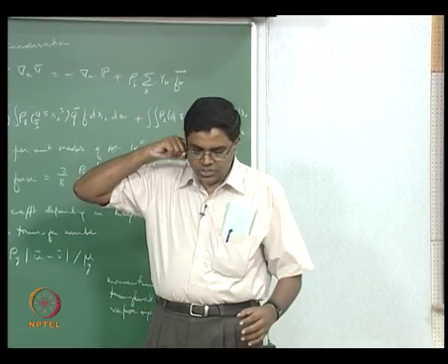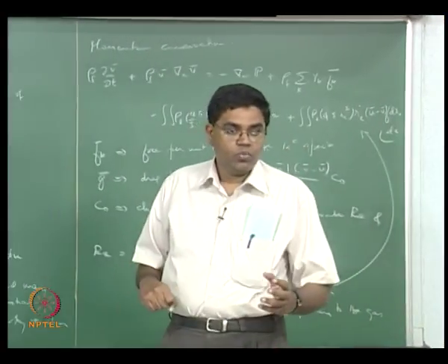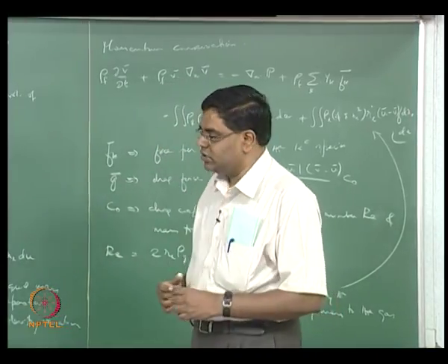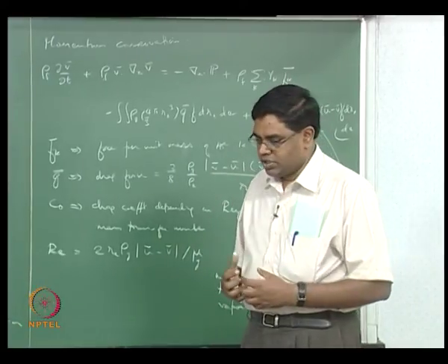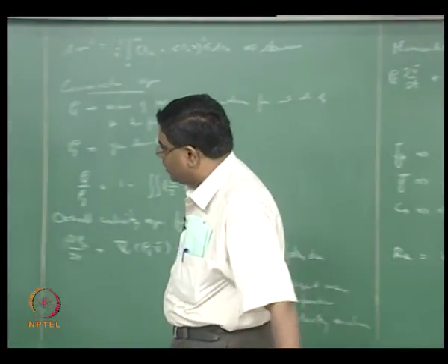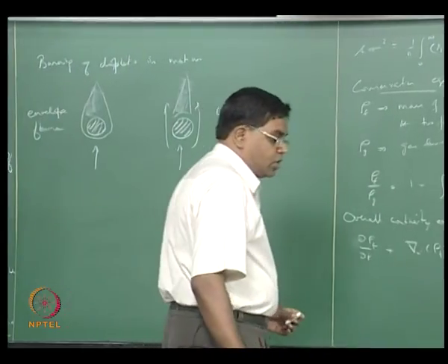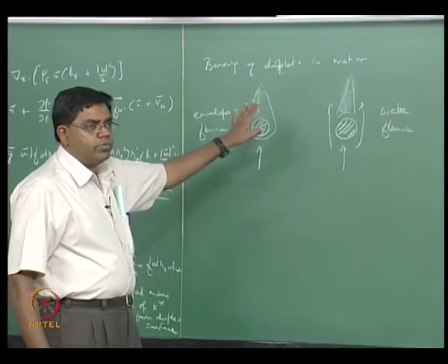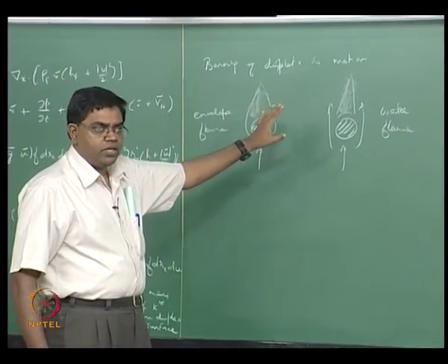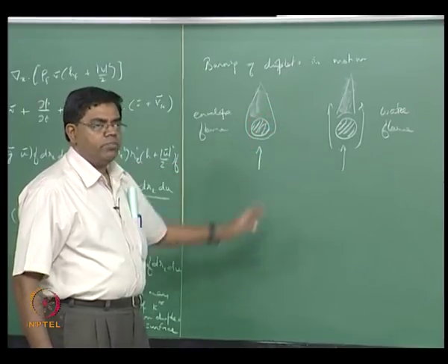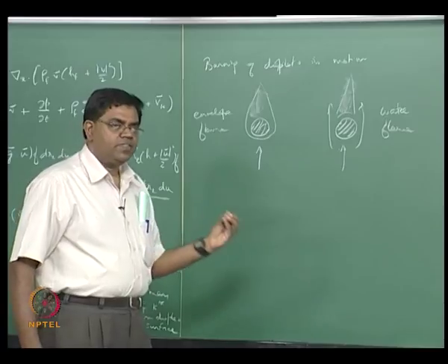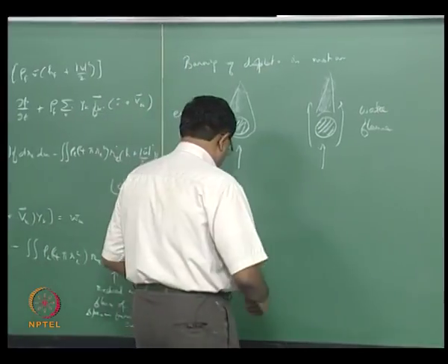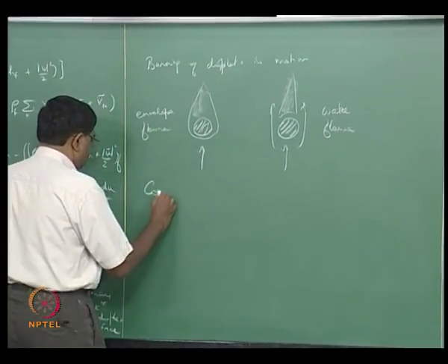And yesterday we mentioned the situation of, let's say, coal combustion, where you have single particle combustion rather than cloud combustion. That is because of lesser volatiles. So I'll just quickly talk about coal combustion and other solid combustion. We also mentioned, for example, metal combustion, where it is similar to droplet combustion, because by the time the metals are actually burning, they melt, and so you have molten metal droplets that are burning. Although it may seem like we are burning solids, in reality you might end up burning liquids. So if you now think about coal particles,